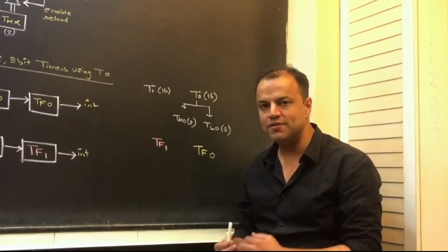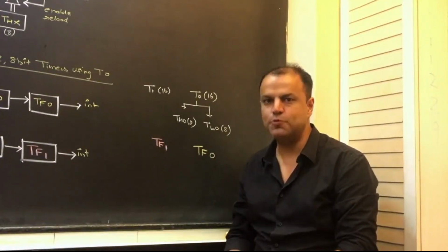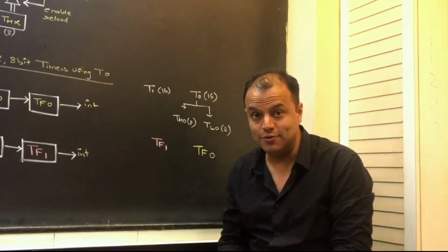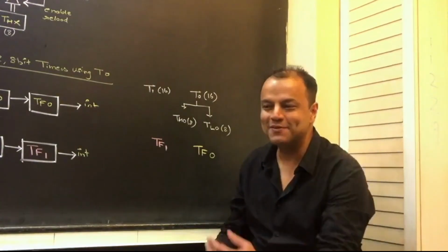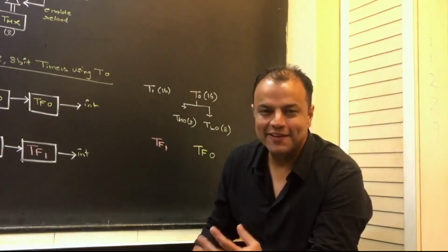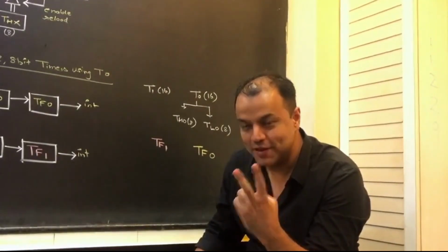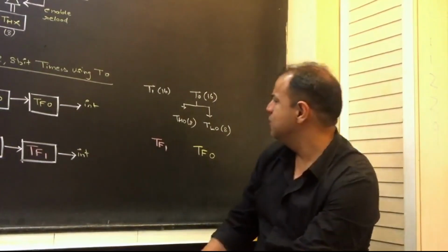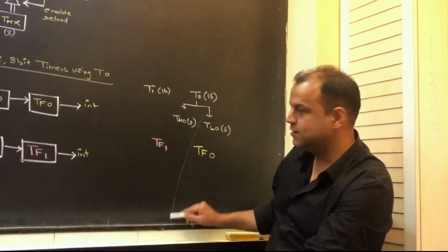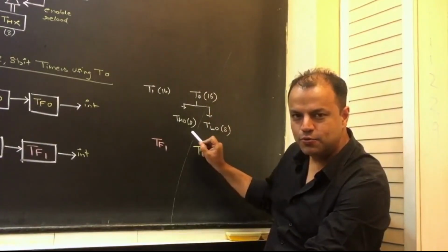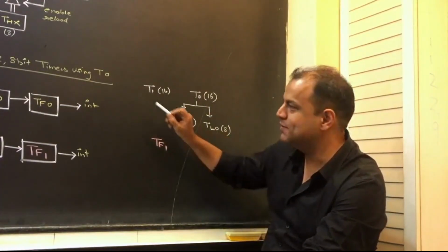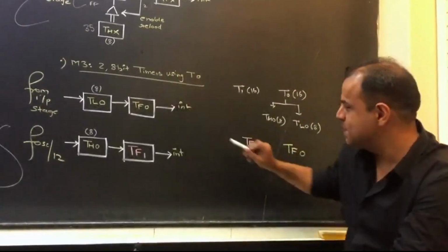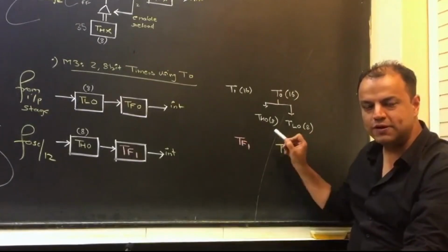Now what we're going to do is ruin this system, spoil this system. Why? Because of greed. Greed, you know what greed is, right? One of the 7 sins. We have how many timers? 2. We are going to create 3 timers. How? We are going to split timer 0 into 2 independent 8-bit timers. That's the name. Read the name again. 2 8-bit timers using timer 0.